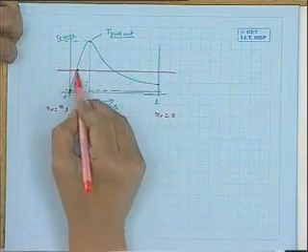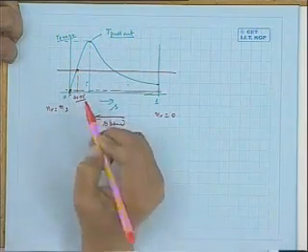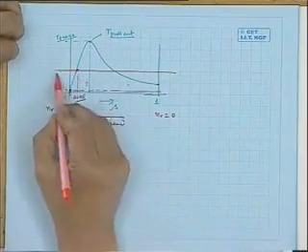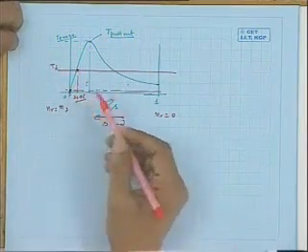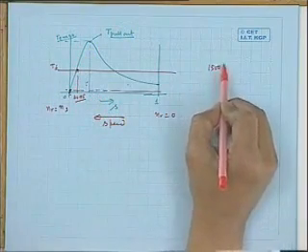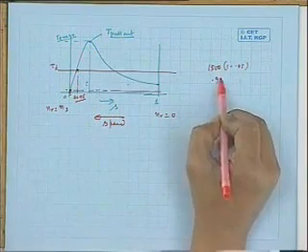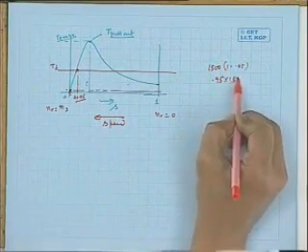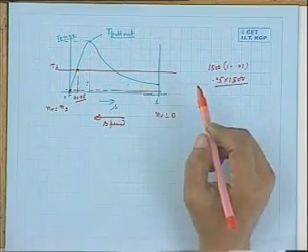And when the machine is operating at full load, say this one, full load torque, about 5%, this is 0.1, so this is say s equal to 0.05 or so, 4%, 5% slip. Suppose this is the full load torque. Then at what speed will the machine operate? Only 1500 into (1 minus 0.05), that is 95% of 1500.